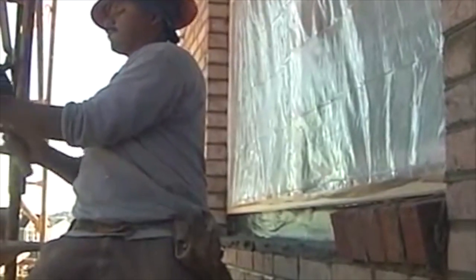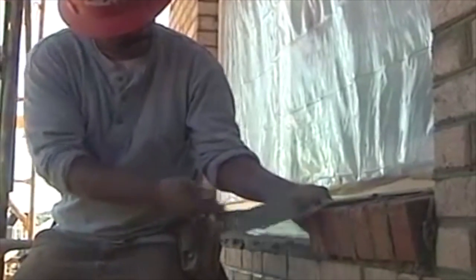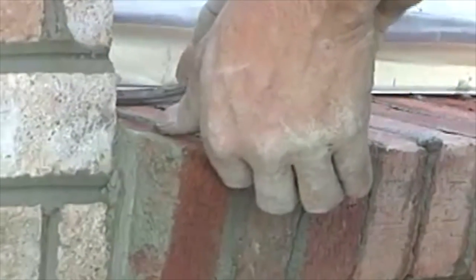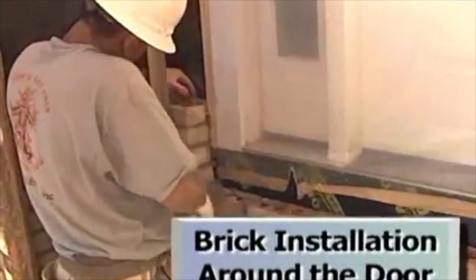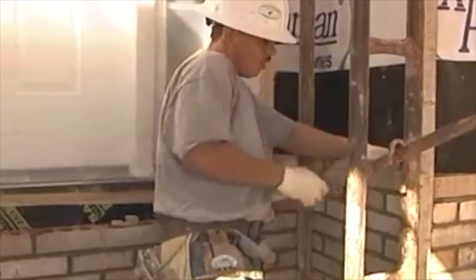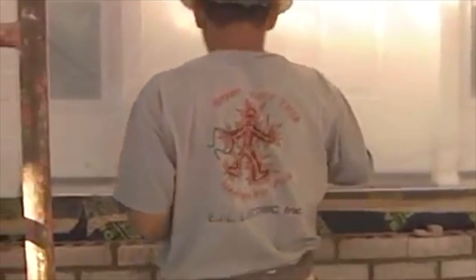A brick window sill is fashioned and anchored to promote the drainage of rain away from the window and the wall cavity. The flashing underneath the door opening will be similar to the window sill area, including a dam fixture and weep hole. This is the detail of the brick cavity wall.